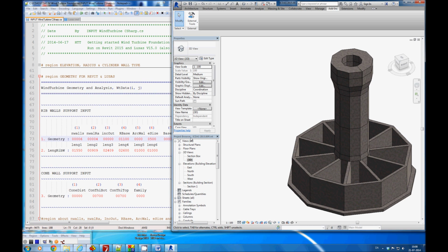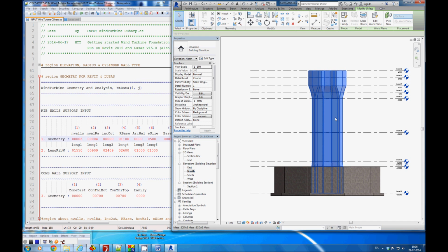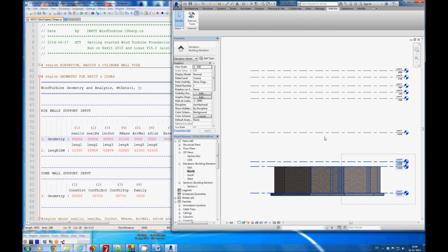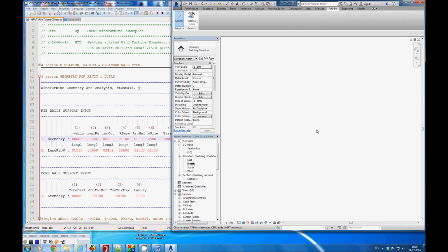In Revit, I go to the project browser, Node, select the current family cylinder and hide it. So I can select all existing levels and walls and delete them in the project file, because I run it again with 6 walls. I go to add-ins, external tools, and create the new.